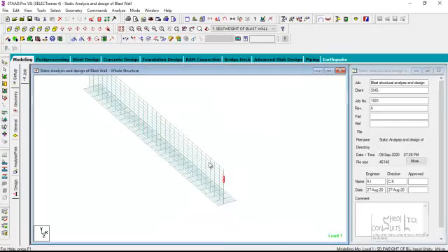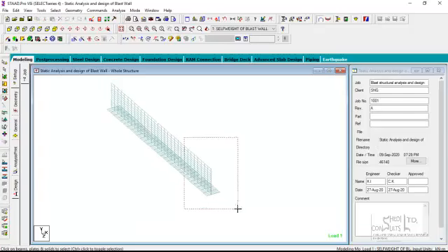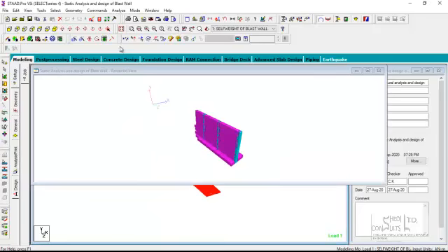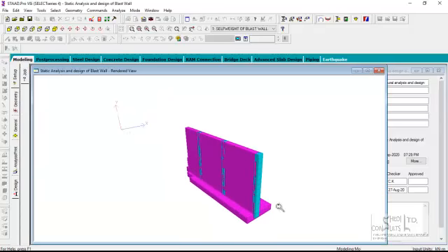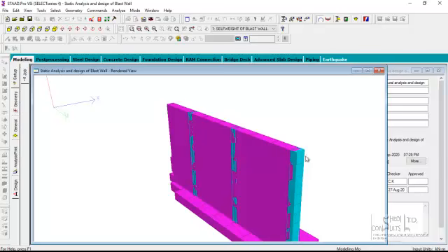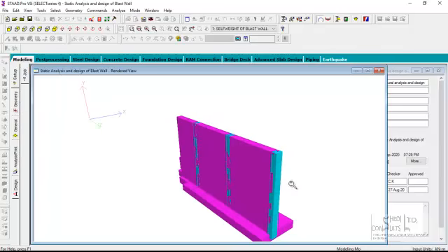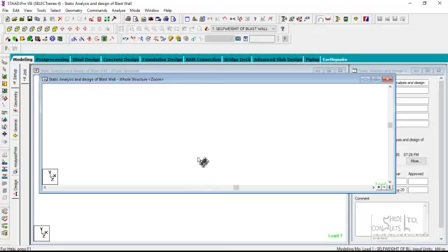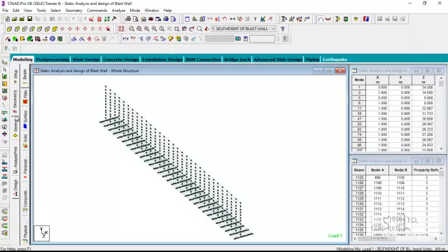Now the 400 is in this direction, so as to gain the direction where it has its maximum moment of inertia. If you look at the representation of the blast wall and look at the columns, you see that the columns are positioned such that the longer side has its maximum moment of inertia about its major principal axis, higher than its minimum moment. So in the event of an explosion, it has more moment resistance against plastic failure. Okay, so these are the properties of the wall.